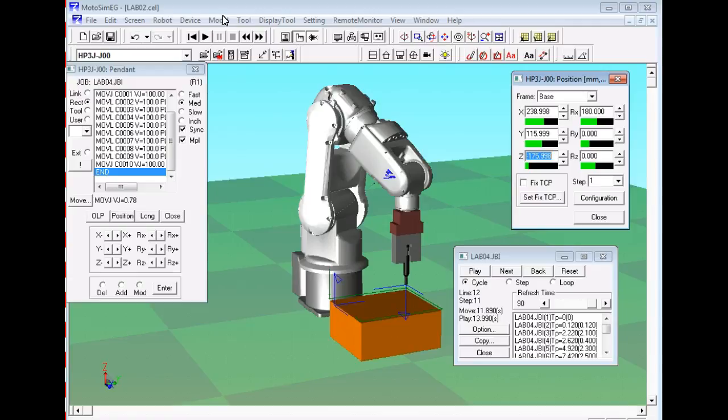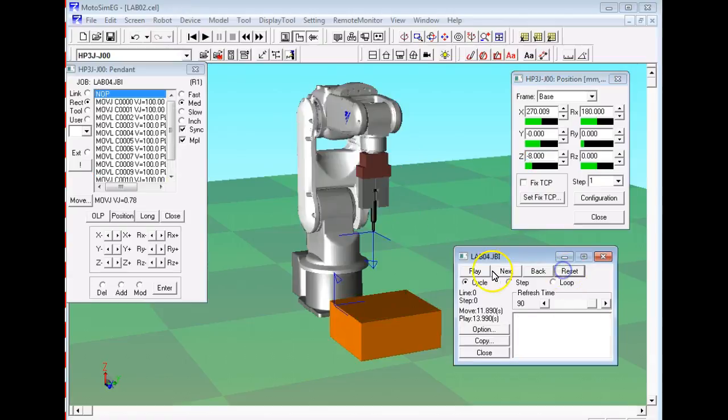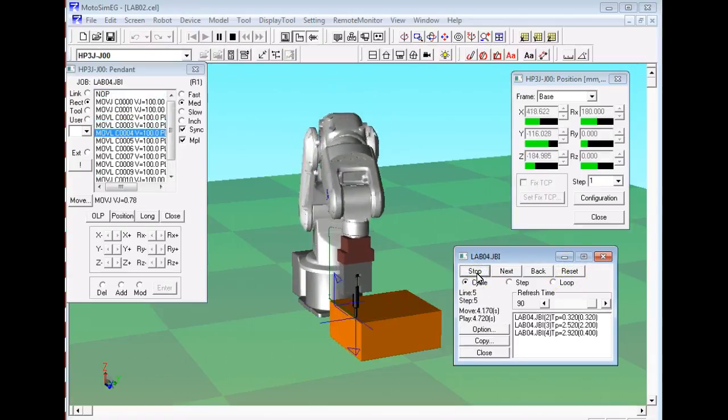Like I said, I decided to show y'all all these programs. I think I do have the program where we modify it. One of the things you're going to do when you modify the program is add a point. So right now you're doing A, B, C, and D. Then you're going to add another line that moves back over to A, and then you're going to reteach those staging points. Right now your staging points are over at D, and you're going to have to reteach them above A, right? So this is one of the first modifications that you're going to make.